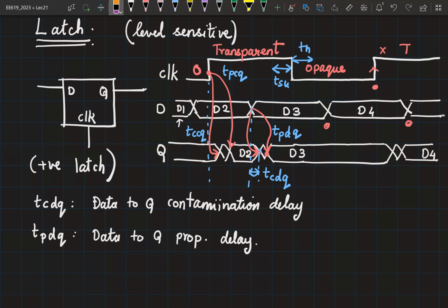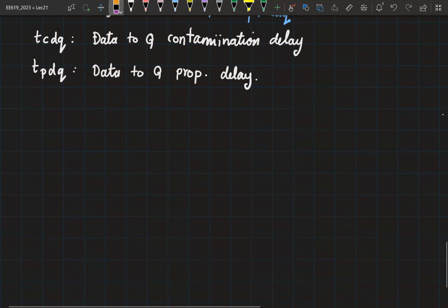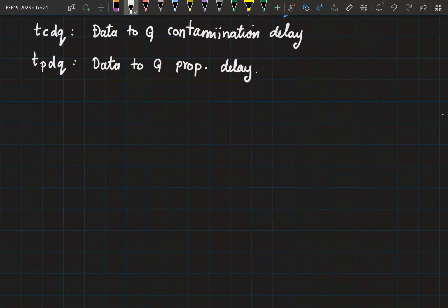Okay, so now we know the definition for a flip-flop. We know the definition for a latch. Any guesses on what a register is? It stores the data for a given time. So that's what a flip-flop also does. More than one bit, right? So a register is basically multiple flops that are tied to the same variable.